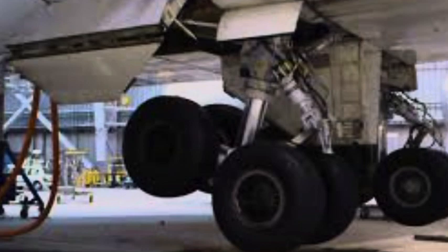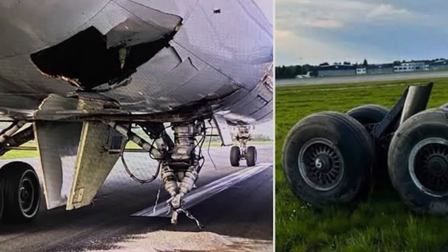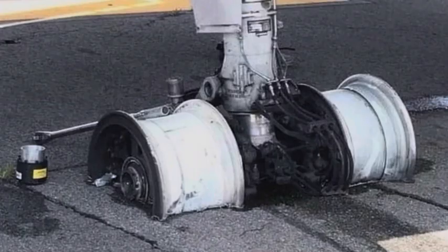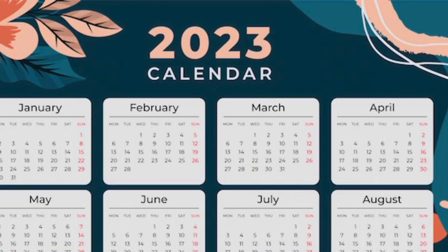This means that when the landing gear is attached to the aircraft, it can have 12,000 landings with this landing gear. In fact, if between 12,000 cycles there is damage, or maybe some hard landings or any other problems, that's another story: the landing gear should be removed and sent back for the overhaul. Otherwise, if everything goes fine, then the aircraft can have 12,000 landings with that newly manufactured or overhauled landing gear.